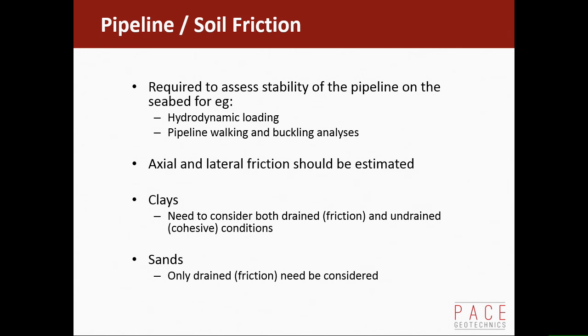Sands are a granular material that work purely on friction, so we only consider the drained case, the actual friction between the sand particles or the friction between the sand and the coating of the pipeline.